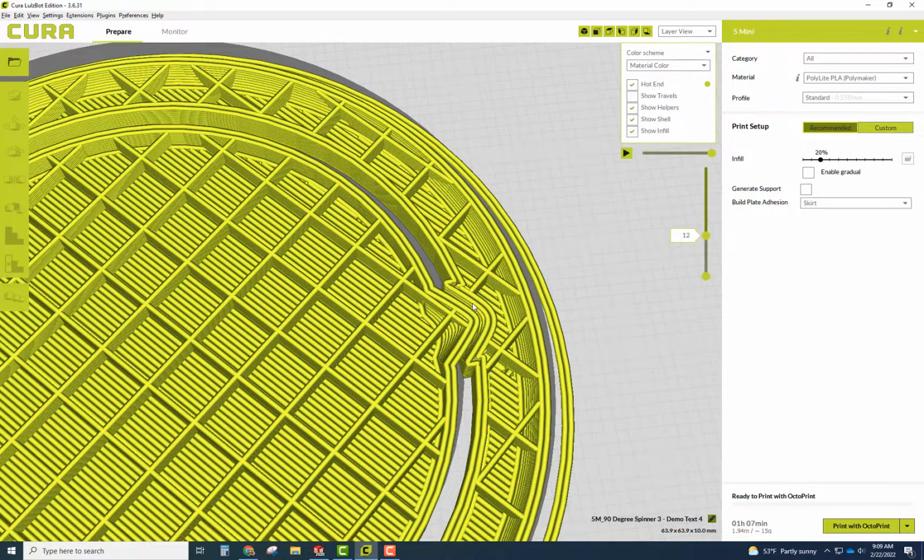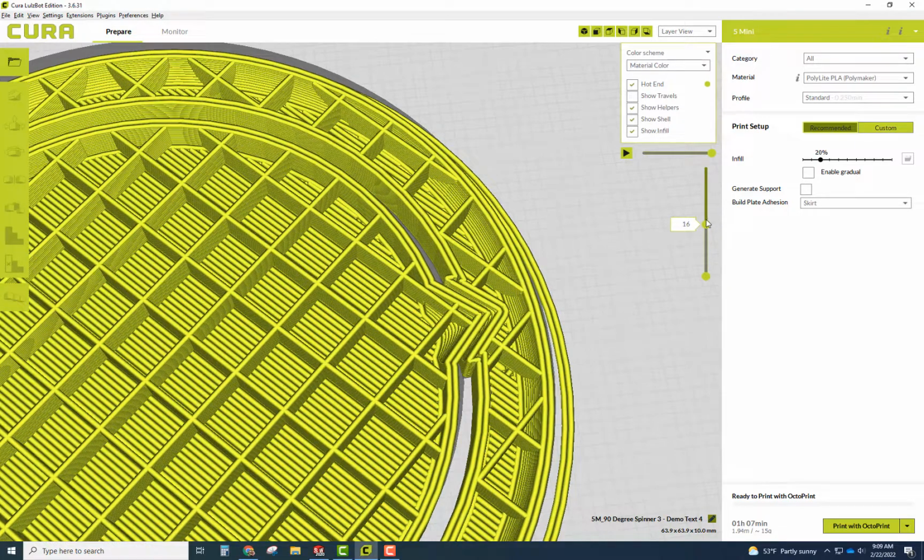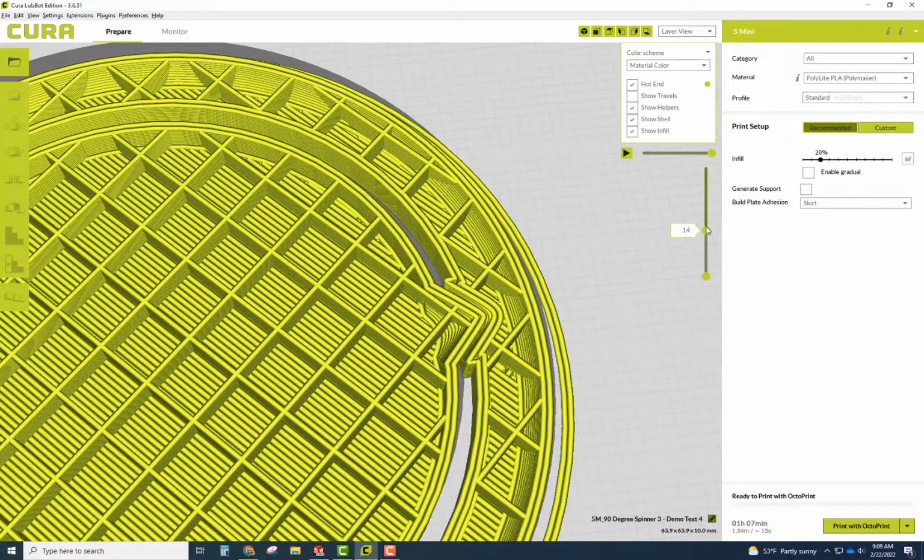If yours does not have a gap, if it's too close together, it may fuse when it's printed. In other words, the plastic will fuse together and create one bond, and you won't have any kind of a spinner. It won't be able to spin. So you want to make sure that gap is maintained. Look back: if it is fused or put together, there's no gap right there.